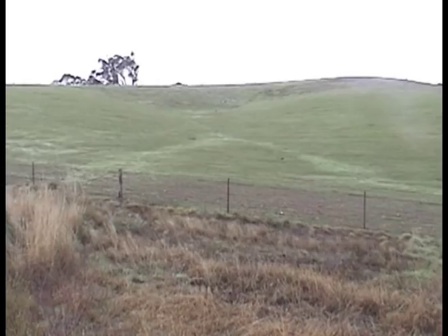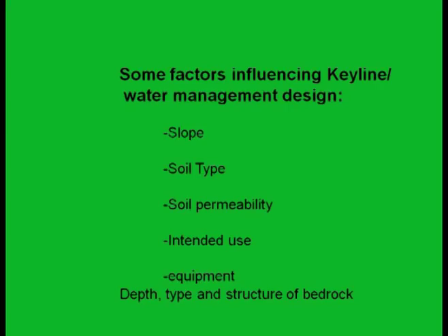And it was fascinating. Some things that are going to influence our water management design is the slope. How steep is your ground? Like that really, really steep one? Or flat? The soil type, sandy soil, clay soil. That determines its permeability. If you're on a super granular, thick, coarse sand, like crushed pumice out in Hawaii or something like that, water's going to infiltrate really quick. That's going to affect your decision making about this.